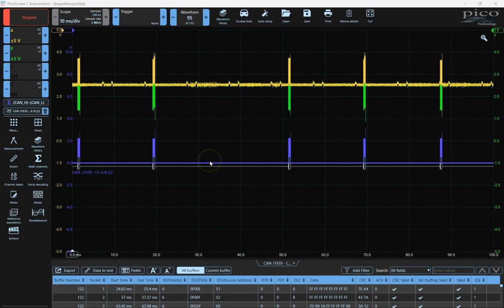Okay, so what I have displayed here is some actual data that I took in the field earlier this year, back in the spring. This is a Hagie sprayer that has a John Deere Power Systems engine in it. And this is the after treatment bus. The after treatment bus consists of 2 NOx sensors, a DEF header, which contains the DEF quality and level sensor, and the engine control unit.